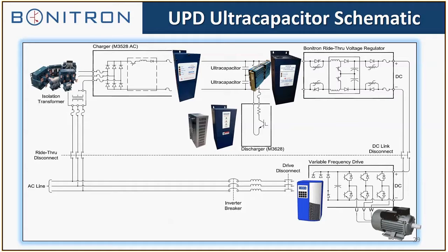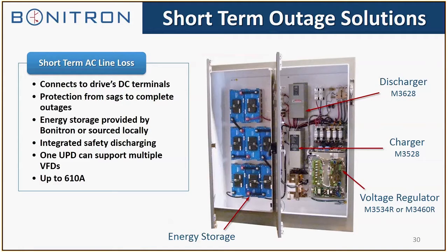And with UltraCap energy storage, these are roughly rated in farads, so it can take a long time for them to just bleed off. So we provide a discharger that will immediately discharge the cap bank in the event of maintenance, or you have to get into the cabinet for one reason or another. This slide here shows the components mounted in the cabinet in more detail. Once again, connects to the drive's DC bus terminals.